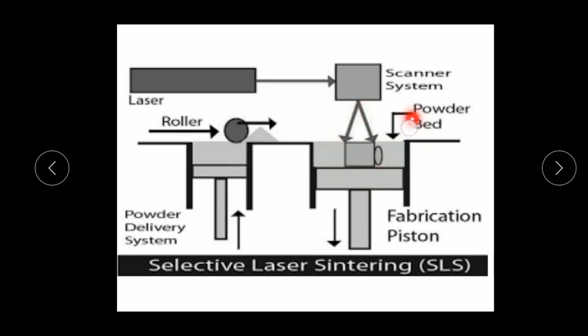Once the design shape is obtained, powder bed 1 again supplies the powder material, and the cavity created by the scanning is covered and filled by these powder raw materials. After the cavity is filled completely and successfully, this piston moves down. Once this piston moves down, it means a certain thickness of layer is already formed, which is called layer 1.